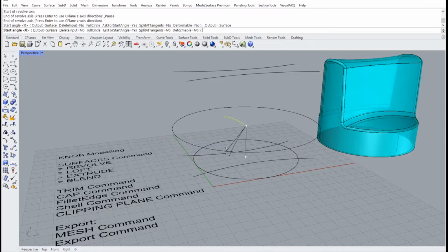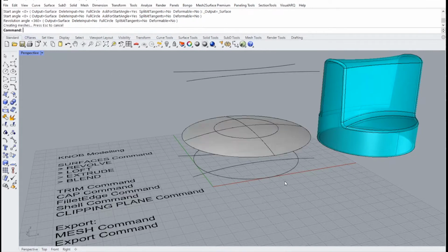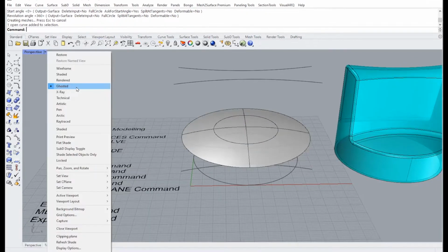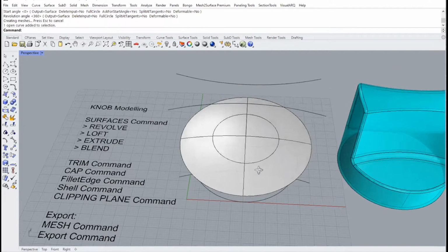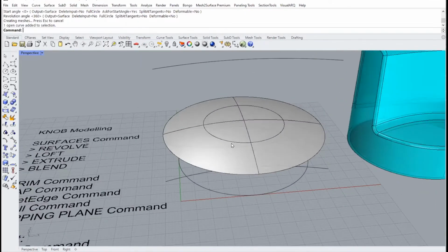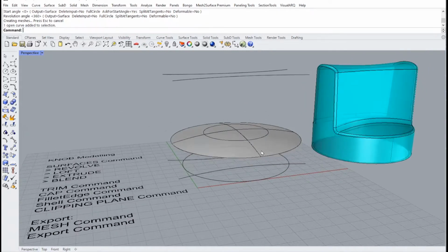And looking at the command at the top here, it says 0, enter, and 360. Yep. So we get a 360 of this. So currently the view that I'm setting, it's ghosted, so that I can semi-see through the curve component at the bottom of the screen of the surface. All right, so let me carry on.